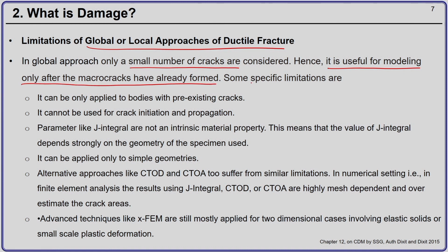There are some specific limitations of the global approach: it can only be applied to bodies with pre-existing cracks. It cannot be used for crack initiation and propagation, although now you can combine it with XFEM kind of approaches, where you can have crack propagation, but mostly it is limited to 2D and very difficult to do in 3D.